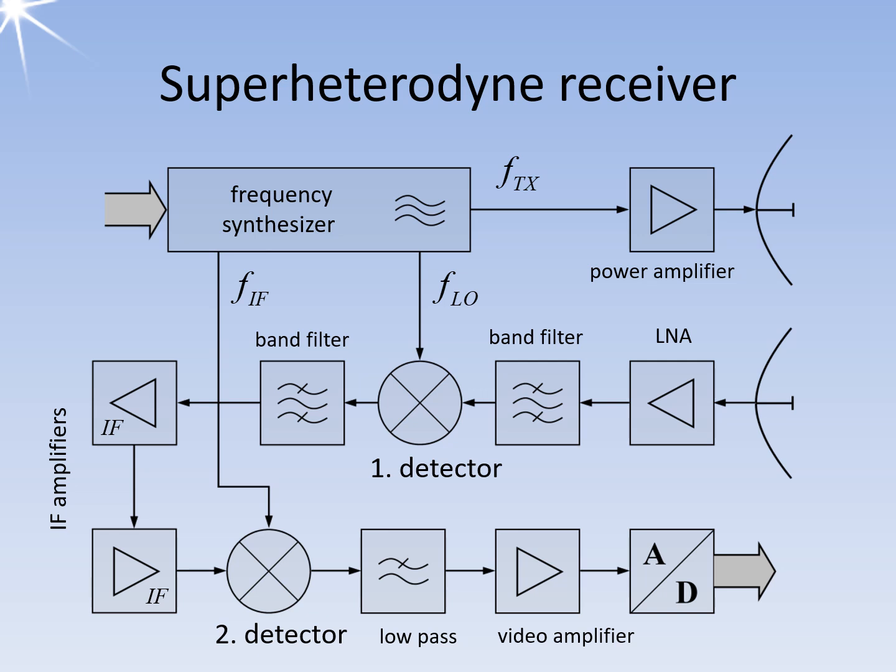The mixing stages are usually referred to as a detector in a radar receiver. The amplification of the receiver essentially occurs in a multi-stage intermediate frequency amplifier. A frequency synthesizer generates 3 different frequencies for this purpose. The transmission frequency, a frequency higher or lower by the intermediate frequency for the first down conversion known as the local oscillator frequency. The intermediate frequency for the second detector.